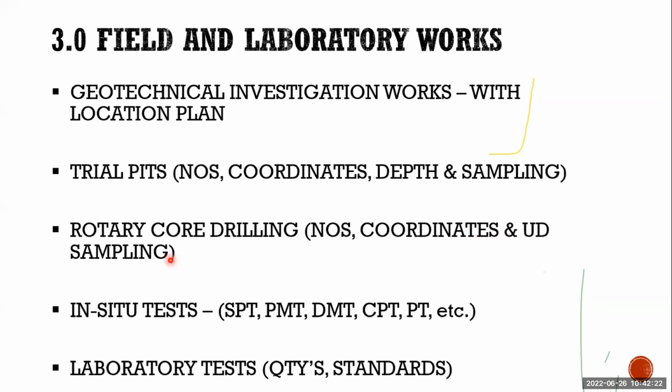And in-situ tests, you have many types. In the core hole, you can do SPT, the standard penetration test, which gives you the consistency of the strata. In BS 5930, based on SPT, we have consistency for cohesive and cohesionless soil. For cohesive soil, it's very soft, soft, firm, stiff, very stiff, based on the SPT values.